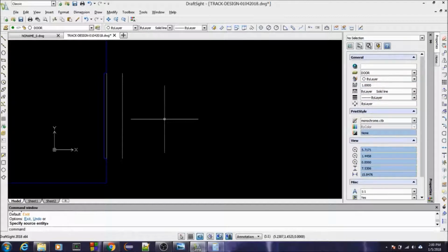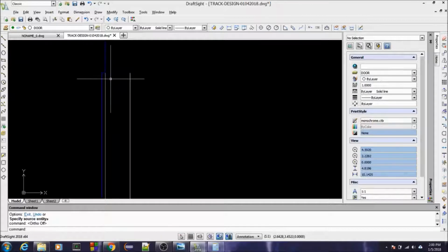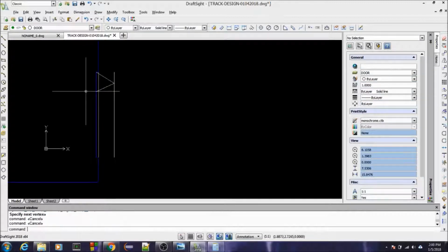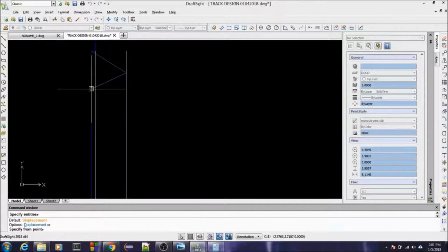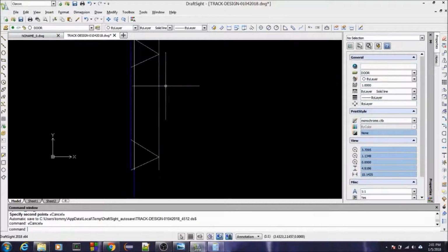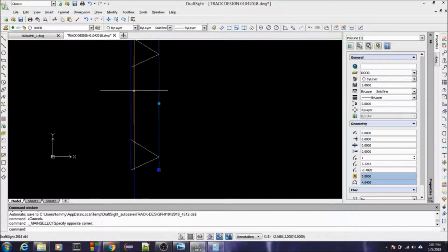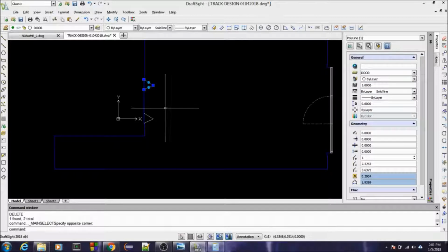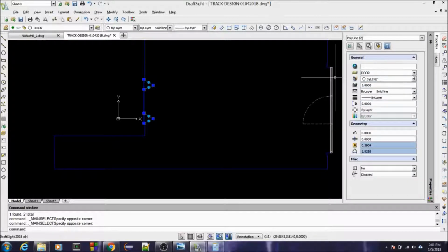Like that. Okay, then I'm going to turn off the ortho command, and I'm going to type in PLINE, and go from this corner to somewhere the nearest on here, say to right there. I'm going to come down and just kind of freehand this. So there we go. Now I'm just going to copy this to here. That would represent our folding doors. And now I can select these and change those to door path as well.